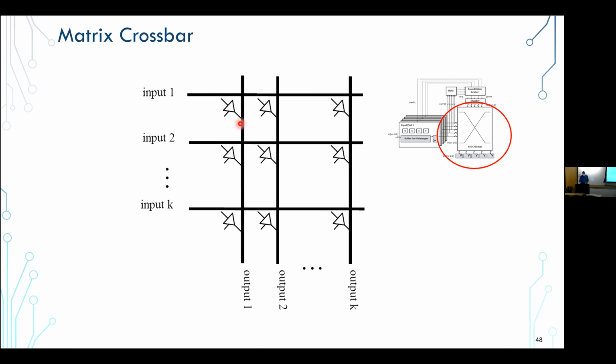The other thing is that notice that even though these are tri-stated, of course, the drain capacitance adds load to the line, right? So you have this increasing load depending on the size of your switch. And if you want to put in a repeater there to buffer the wire, now you have even more density you have to deal with, because now you need some space for the repeater, right? To put it down, remember there's another wire, let's say sitting here. There's a bunch of wires in one direction and a bunch of wires in the other direction. So these in general are hard, even though they look like a nice solution.